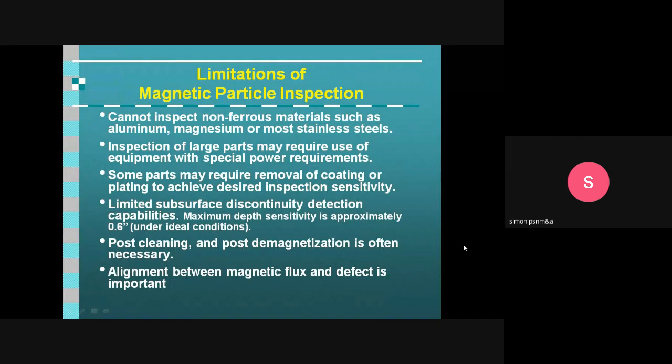Some parts may require removal of coating or plating to achieve desired inspection sensitivity. So in order to have high sensitivity, the coating on some materials has to be removed or the plating has to be removed to improve the sensitivity. Limited subsurface discontinuity detection. So the maximum depth of sensitivity is 0.6 inches. So anything deeper than 0.6 inches cannot be detected.